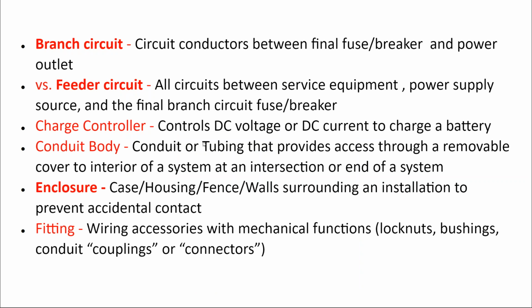I'm going to start picking up the pace a little bit. A branch circuit is what electricians call the circuits in your homes, but there's a certain kind of circuit called a feeder, which transfers power from one distribution panel to another. So, many small homes just have one service panel, and there's a feeder circuit going into that panel from the utility, and then branch circuits coming out of it. But on larger facilities, you might have a series of disconnect switches feeding a series of distribution panels, and that would be a feeder circuit.